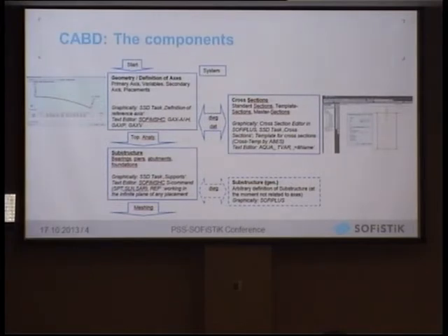There are different tools, again, to model this parametric bridge model. So we would start with maybe something like a graphical input of the general road alignment, the axis, using a graphical task, using the mesh generators, or we might be working with a pure DWG, so Autodesk, AutoCAD-based input. So we might be using our graphical cross-section editor to input what we call the master cross-section.